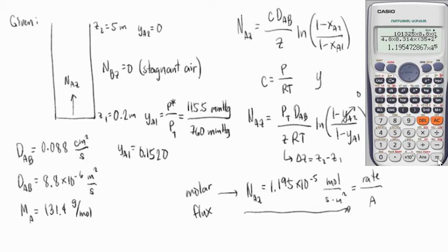The area of transfer in this case is the cross-sectional area of our cylinder. Therefore, we solve that as pi over 4 d squared. Our degreaser has a diameter of 2 meters. Therefore, we can easily solve for its cross-sectional area. So we can now say that our rate of transfer is simply equal to our molar flux multiplied by the cross-sectional area. So we have here our molar flux. I'm going to multiply that with pi over 4 times diameter squared, that is 2 meters squared.